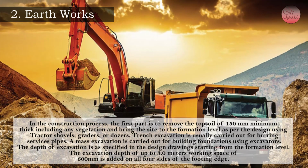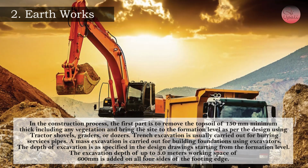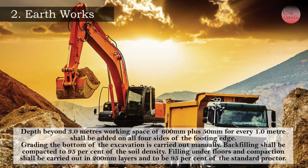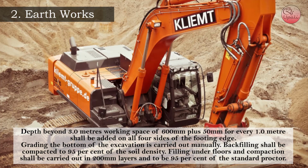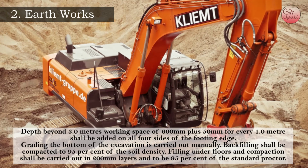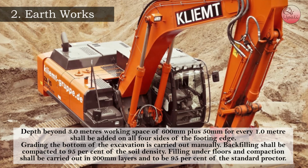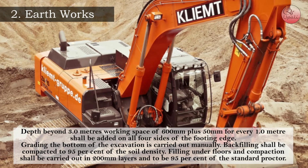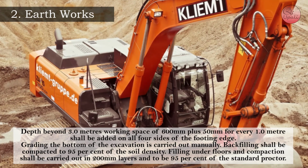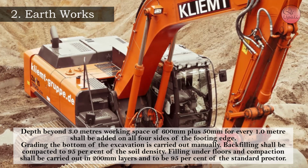For excavation depth of up to 3 meters, a working space of 600 mm is added to all 4 sides of the footing edge. For depth beyond 3 meters, a working space of 600 mm plus 50 mm for every 1 meter shall be added on all 4 sides of the footing edge. Grading the bottom of excavation is carried out manually. Backfilling shall be compacted to 95% of the soil density. Filling under floors and compaction shall be carried out in 200 mm layers and to be 95% of the standard proctor.